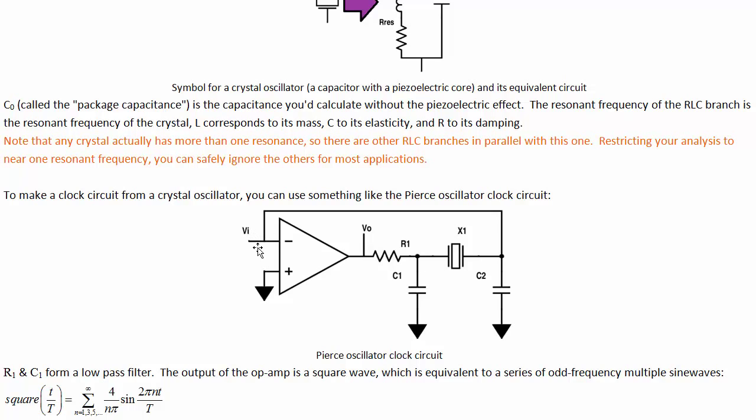This is really just labeling VI. We're not actually setting a voltage in here, and we're getting the voltage out here relative to ground, and because of the behavior of the op amp, drawing a current from here doesn't affect this, but we have to be careful on this side because maybe drawing a current there would affect the rest of this. So we may want to put this into something that has a high input impedance, like another op amp. Okay, or like a flip-flop's clock input, something like that.